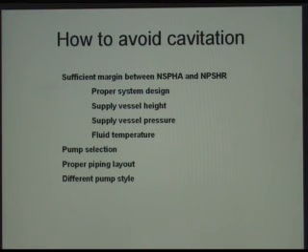So pumps that have different NPSH requirements, is that a function of that localized pressure drop where we have the acceleration? Different pump designs and styles have different NPSH requirements, and that's a function of the geometry of the impeller and the geometry of the inlet, and it's a function of the geometry of the pump. So it is a function of that localized pressure drop then? Yeah. It's more important for those centrifugal pumps.